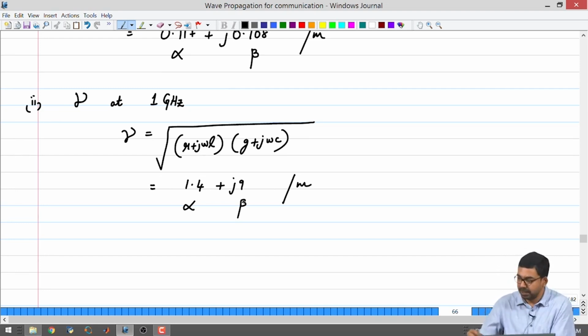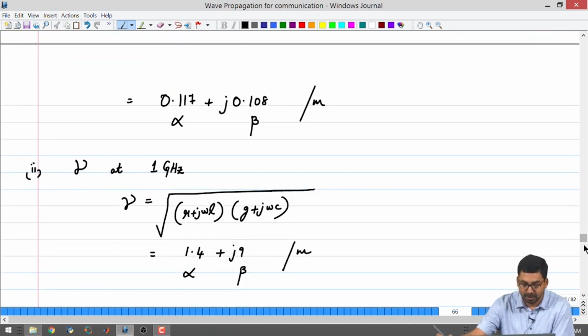The first thing we notice is that in the transmission line, for a lower frequency, the attenuation constant is very low. For high frequency in the same transmission line, assuming all the parameters are fixed, the attenuation constant is very high, which is consistent with the data sheet that we were seeing for the cables. However, I have just picked one of the poorer cables at a particularly bad frequency, but nevertheless, the tendency is